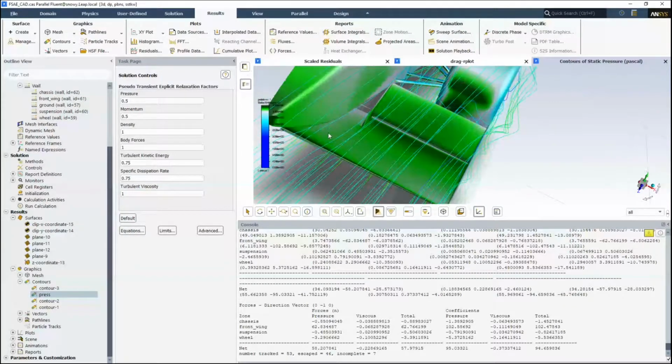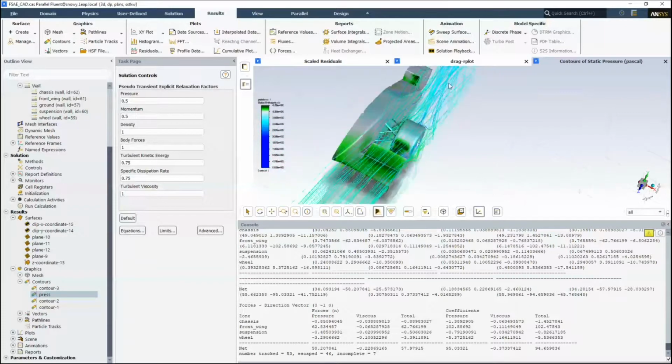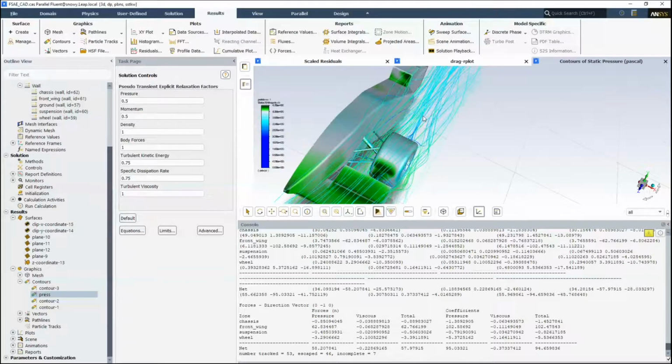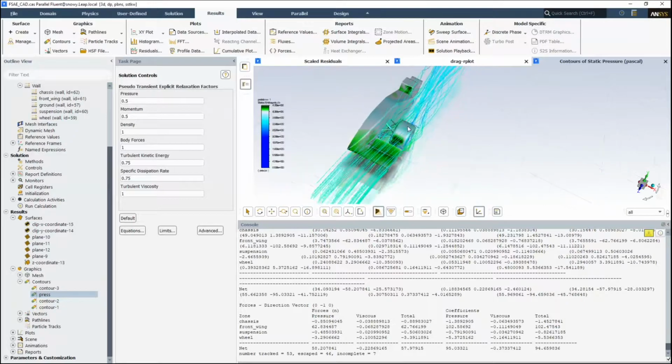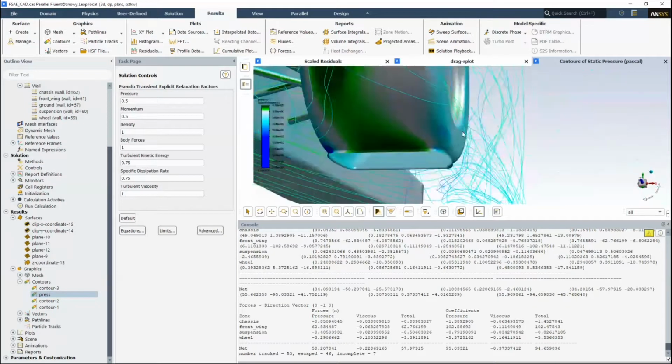And you have quite high energy flow that pushes the vortice, and then they use barge boards to push those vortices out. And what that does is it takes this kind of wake region and moves it away from the vehicle. This low energy flow goes away from the vehicle and opens it up for more high energy flow to come in and hit the lifting surfaces. Okay, so streamlines are a really good way to ascertain where that flow is going and what it's doing.